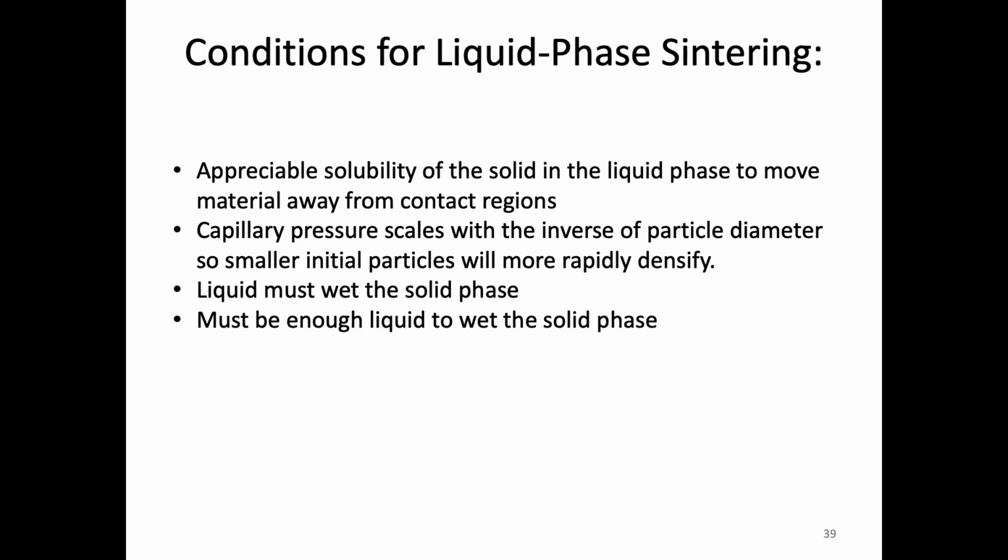So, there's a lot of advantages, but keep in mind when I initially talked about some of the properties that we can get for sintering, having this liquid phase, obviously we've seen it's great for rapid densification and so forth. But if we have a high temperature application, we can run into the influence of that glassy or liquid phase at lower than normal temperatures. So these are typically not going to be used for high temperatures because we run the risk of liquefying that glassy phase in between the solids, and that can reduce mechanical integrity. So we can decrease creep resistance and so forth. And so those are all issues that we have to think about.